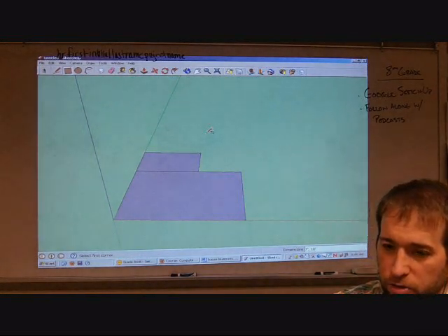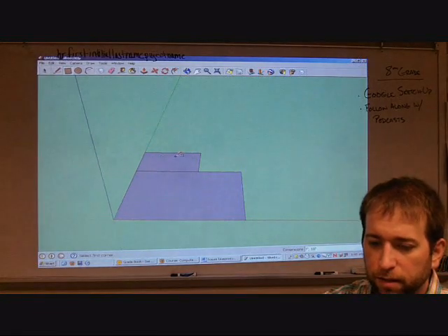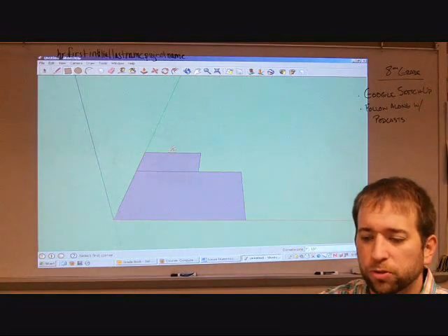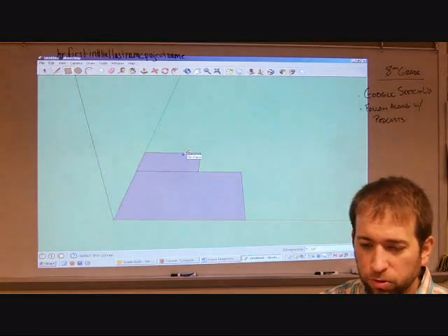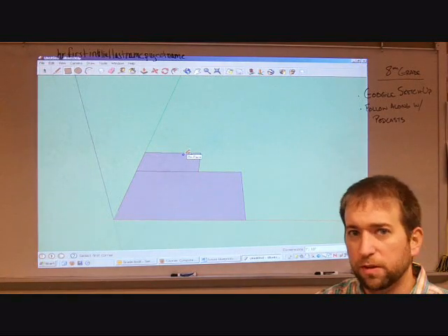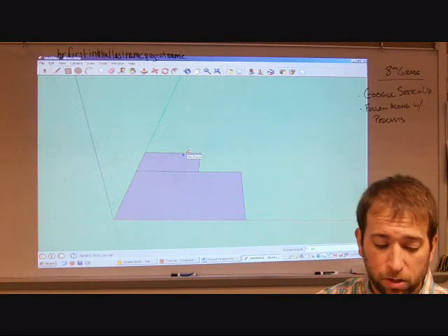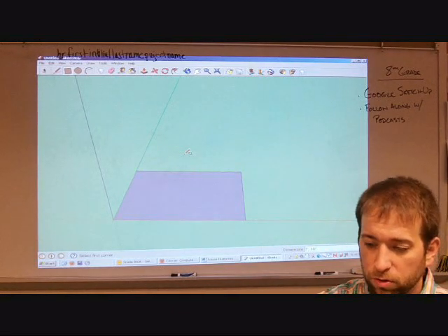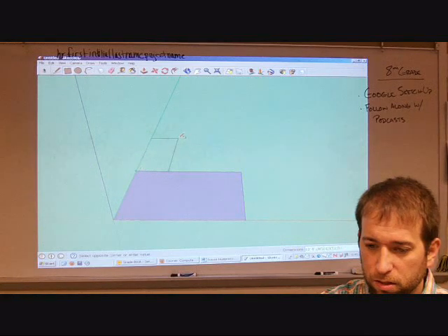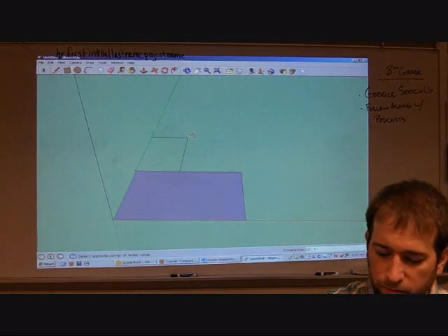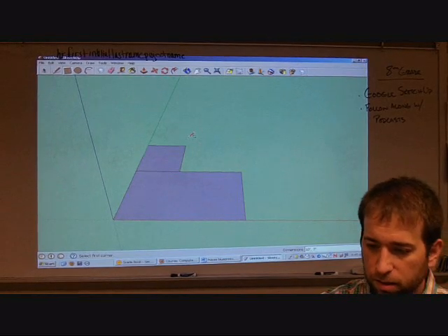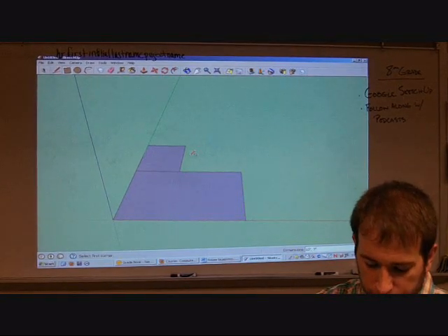Okay, and as you can see, my bathroom that I drew should be more vertical than horizontal. So I'm going to undo that and then flip the numbers around. Instead of 7 by 10, I'll do 10 by 7. So I'm going to hit Control Z to erase it. Draw it again, 10 feet, comma, spacebar, 7 feet. And that looks a little better.